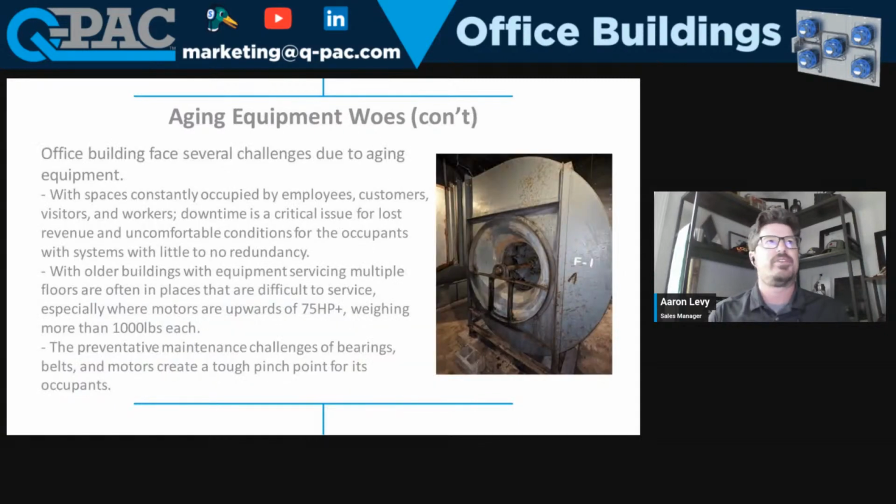Next. And when we talk about aging equipment, this is stuff that you see pretty regularly: double width, double inlet blowers, belt drive systems with pillow block bearings. Some of them still have, in 90% of the cases, probably non-working inlet guide vanes. So all this stuff that has broken over the years, that nobody either wants to fix or doesn't really add any value to their system, is just still there, rusting and getting older, and all the efficiency they're losing.